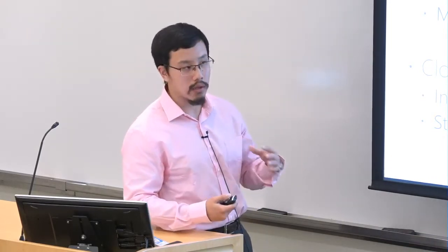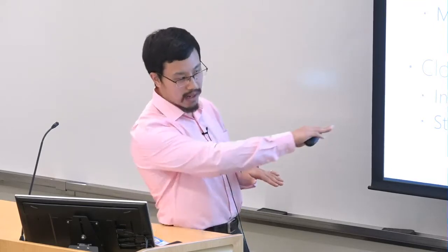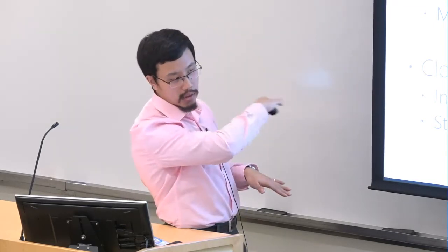And with a better pose tracker, we can do more human-environment interaction, such as odometry on IMU. We all know using IMU to do odometry is not reliable because of the internal drift and the sensor noise. But we may be able to compensate for the noise using multiple sensors and also different sensor modalities. We can also do graphical SLAM. Say the person is interacting in a room, in a hallway or in a map; how could we build a graphical map of it based on my odometry? Multimodal SLAM is more like including an ultrasonic sensor to do one-layer mapping of the occupancy grid. It's also portable if we have a good pose tracker.